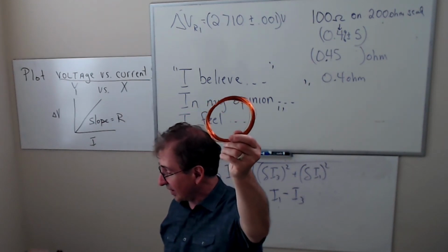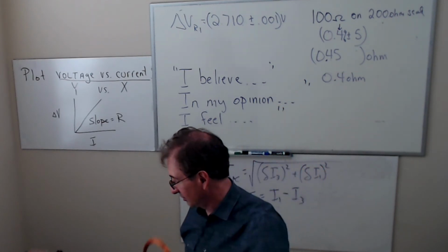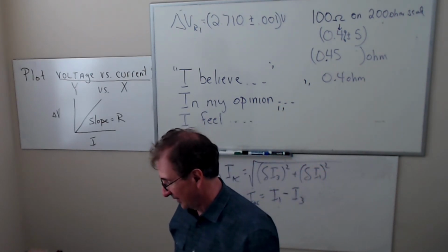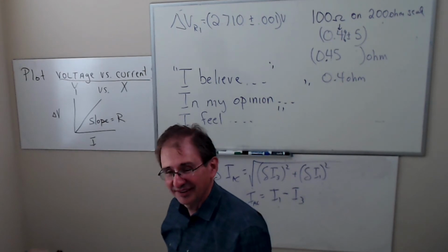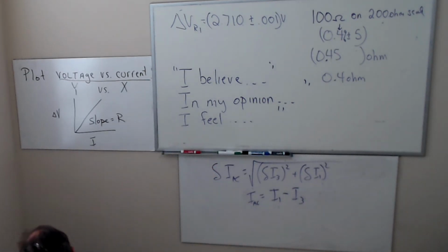But of course, the enamel melts. If you put too much current in this thing, you will melt the enamel. And then you need more magnet wire, because you're going to short things. I forget how many feet this is. I think it's 30 feet of wire, if I remember correctly.